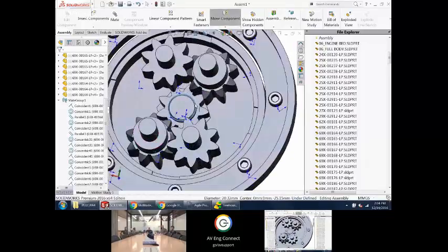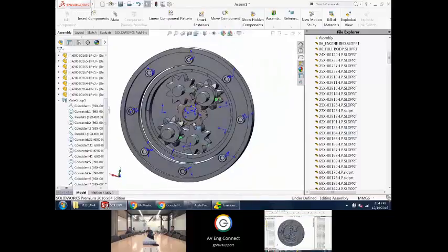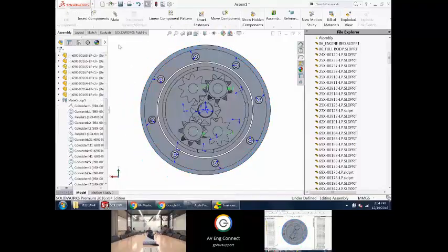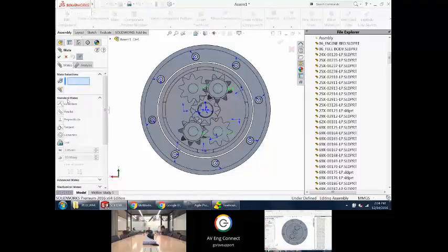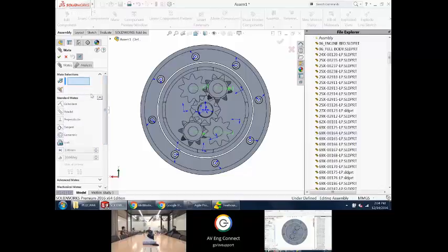So these are gears. I would like to make them. There are a lot of different types of mates in SolidWorks. Obviously, coincident, concentric, parallel, perpendicular, those kind of things speak for themselves. There's other types of mates besides the standard mates. There's advanced mates, like a width mate and a profile center. I'll show you the profile center because it's pretty cool. But symmetric, limit mates, things like that, these take much longer to solve than your standard mates. Again, standard mates are pretty cut and dry.